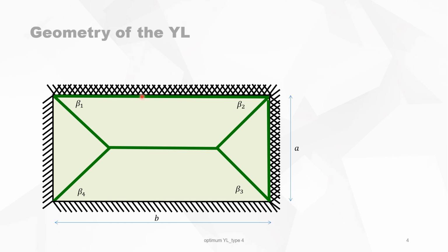When this is not the case, instead of M you can use M1, which is a proportion of M, and then you can redo the calculations. But because we normally find it attractive to give the same reinforcement on top and bottom of the slab, the assumption that M on the bottom is equal to M on the top is realistic.